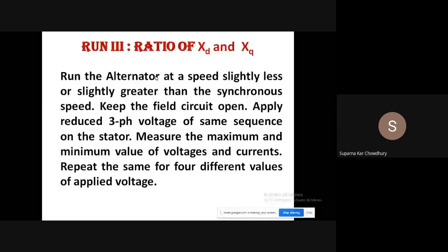Now, as both the stator and rotor are iron structures, most of the MMF is consumed by the air gap. So in the direct axis, as the air gap is small, the reluctance offered is small. We have applied a constant voltage, so flux is constant. So for creating this flux through the small air gap, we require a lower magnetizing current.